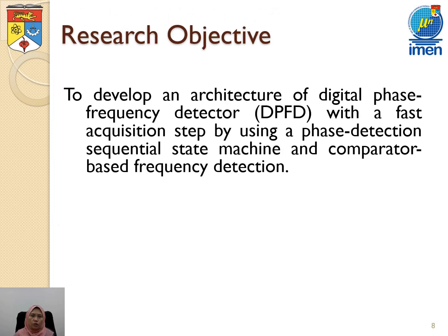Therefore, our research objective here is to develop an architecture of a digital phase frequency detector with a fast acquisition step by using a phase detection sequential state machine and a comparator-based frequency detector.